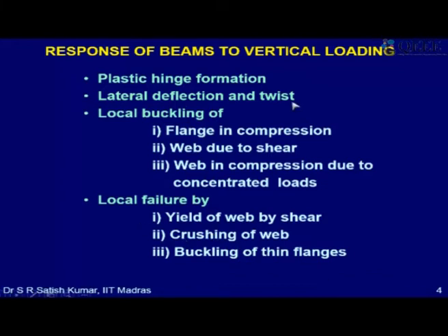So if you don't want this to happen, we have to give lateral support to the beam, right? So that's something which we'll have to do. The other option is we need to calculate the strength taking lateral buckling into account. Okay, so these are the two possibilities.